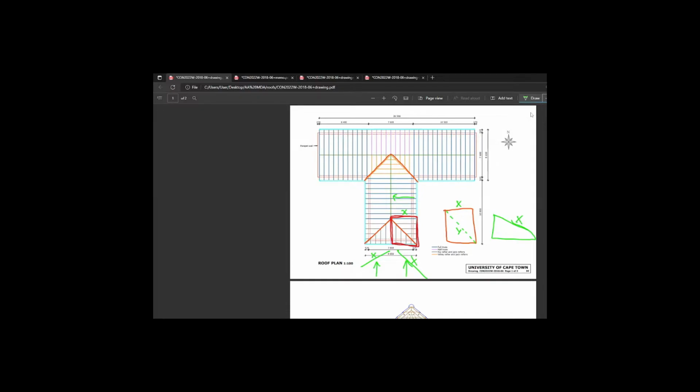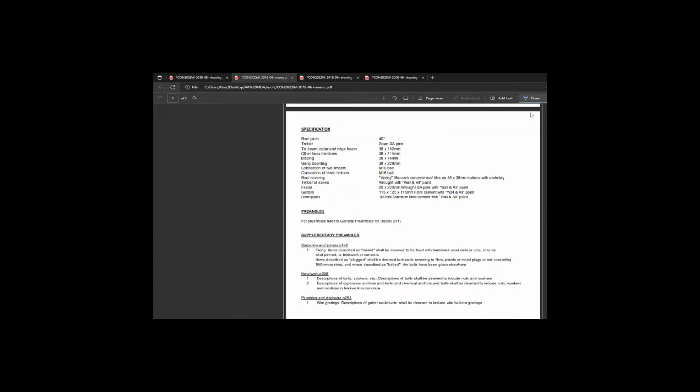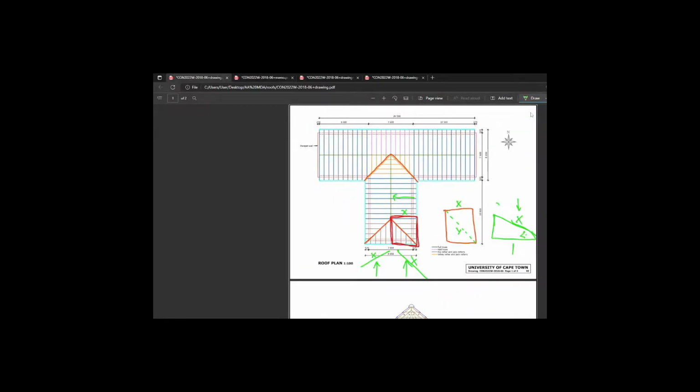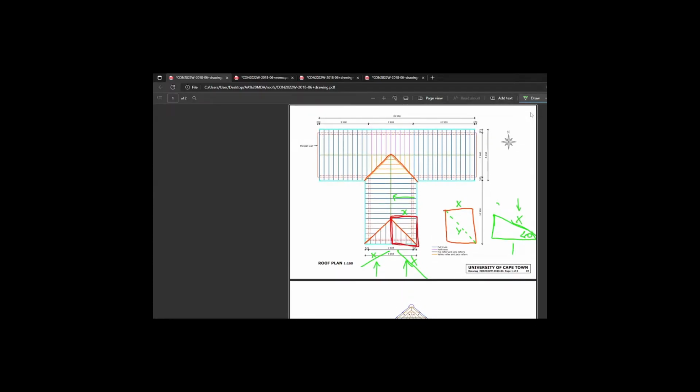If a factor for x, or the actual value for x, you can decide. We say for 1 unit here, what would x equal? So let's bounce back, we need to find out what the pitch of the roof is, 40 degrees. Okay, there it is. So it's given as 40 degrees. And from here, it's a pretty basic trick, but you need to keep track of what you're calculating. So we're currently doing x leading up to the apex in a straight line, so perpendicular. Right? Perpendicular to our ridge. First.